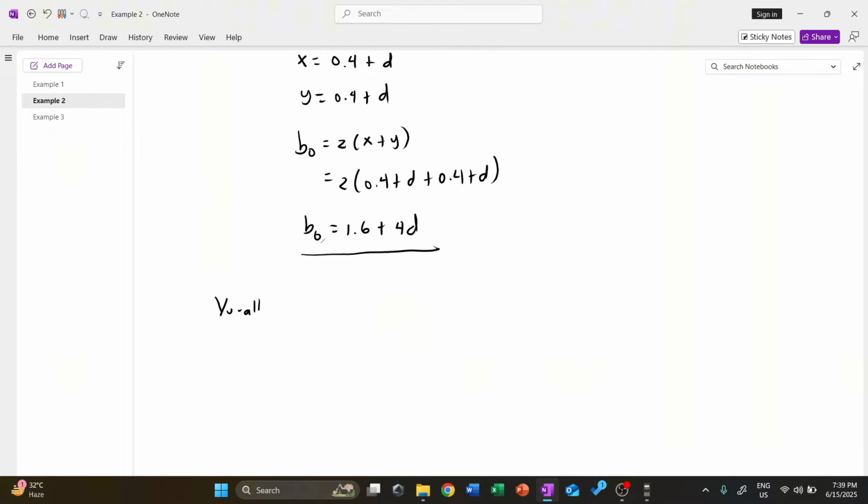Okay, so the same again: our VU allowable is equal to the VU actual. Our allowable is still phi VC. Then our VU actual is QU times the shaded area, still. It doesn't change; whether punching or wide beam, the formula is the same. What changes is the shaded area and the value of VC, the allowable VC.